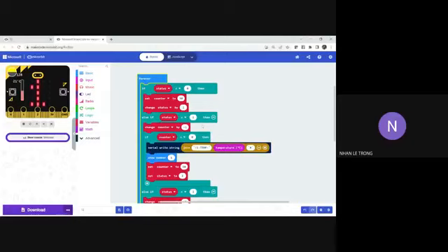What we need is to structure the source code in a way that is very easy to debug and very easy to improve. So like, I want you to add one extra function to control an LED. You just need to implement a second state machine and put everything in forever. The idea of the state machine is that at a given time, just one of the steps is executed.